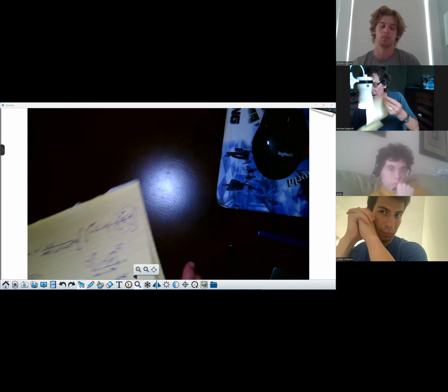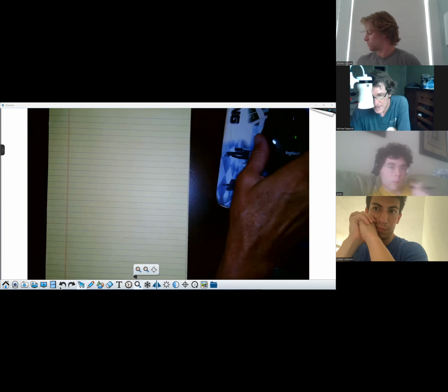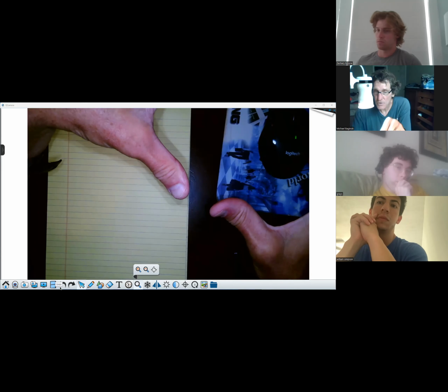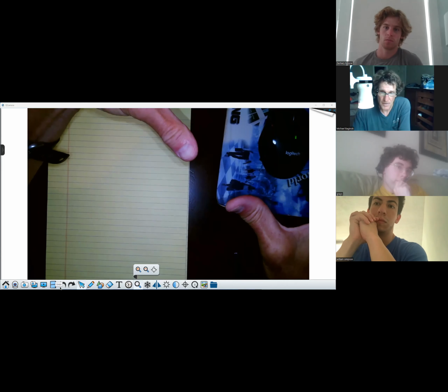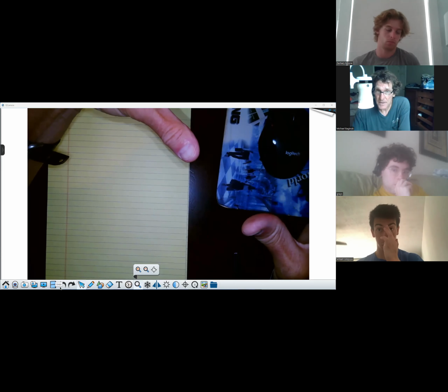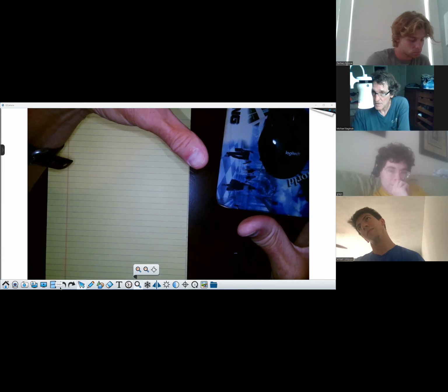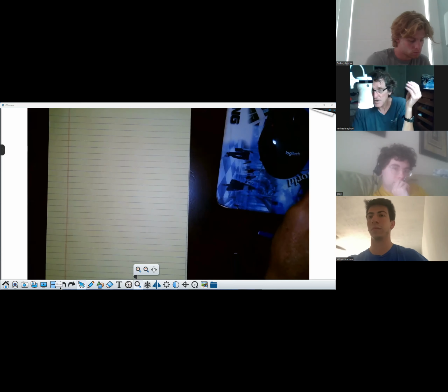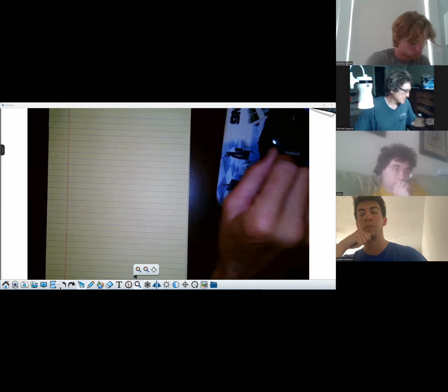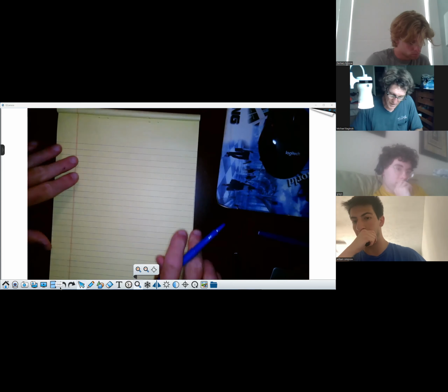Next, we're going to do the infinite lines. Now, do you all recall the parallels? Remember when we had a loop of charge, what the E field was? The difference is the E field goes to 0 at the origin for a loop of charge, right? Here, the H field's a maximum. And the other thing is, for a loop of charge, it's the same type of integral, but there's no cross product. I'll try to contrast these things. Do you at least have an idea what I'm talking about there? Yeah.